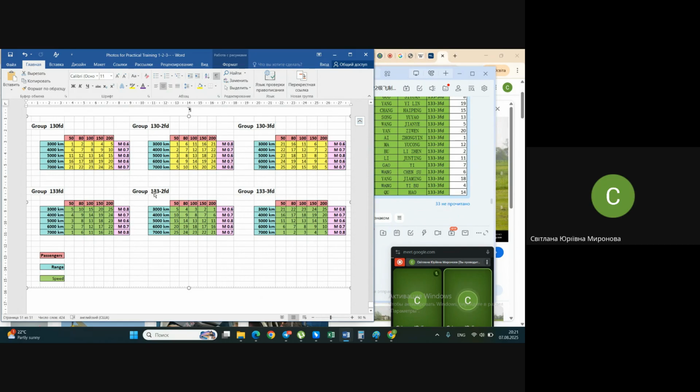For instance, you see prototypes with the appropriate number of people, but the range is not exactly yours. The range of the airplane that you need to design is greater than you have found in prototypes. What does it mean for you? Let's use brains. It means that you need to increase the relative weight of the fuel, at the account of what you may reduce.